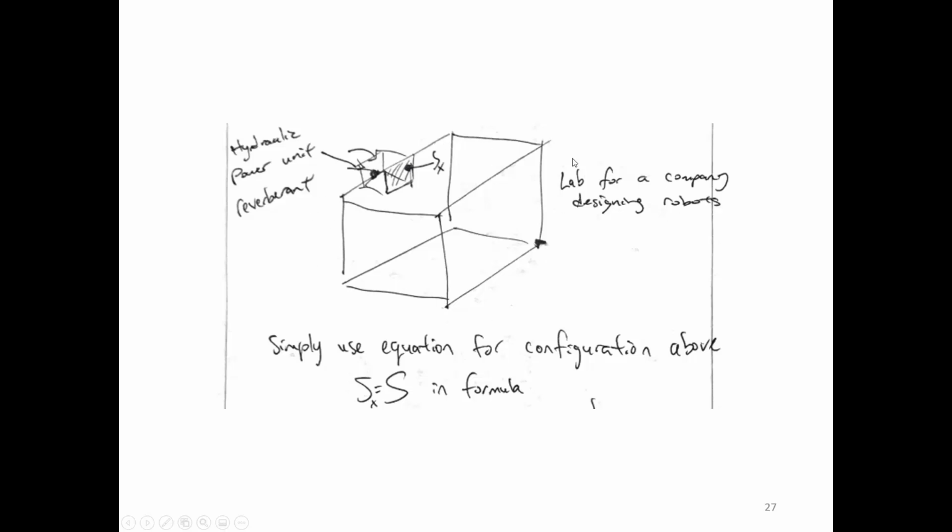It's a big room, and then they have this mechanical room up here. They have a hydraulic power unit in this space, so it's a reverberant space. The sound pressure level throughout here is going to be pretty similar. It's the same over this entire wall. So this would be your S in that equation for your noise reduction. And you'd have your sound pressure level in the source room, your LP1.